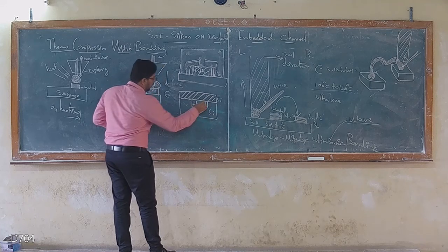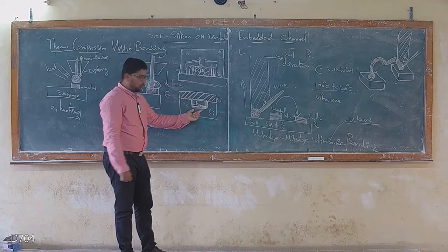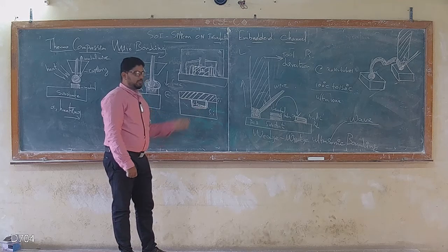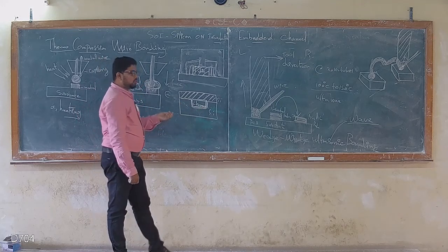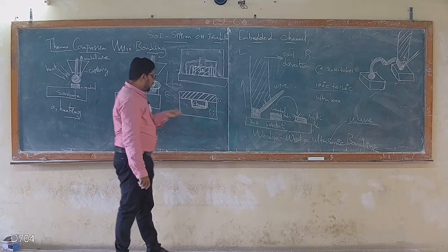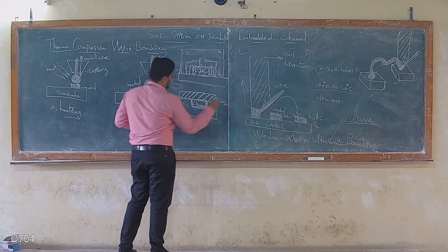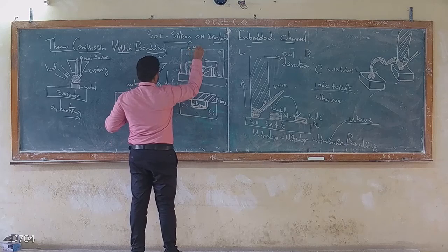I want to create a tight sealing, which means I should protect this void, or this channel will allow some special liquid or gas to flow in microliters, nanoliters. So I should worry about sealing because sealing will ensure the bonding between silicon and silicon dioxide, whereas this is encapsulation.